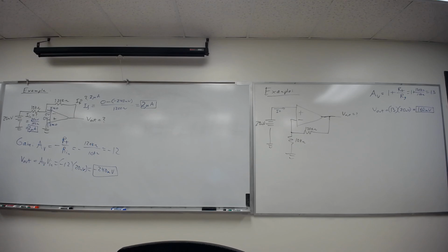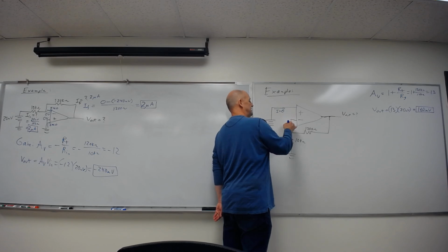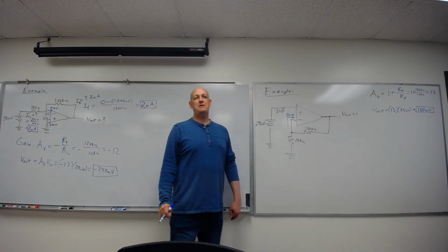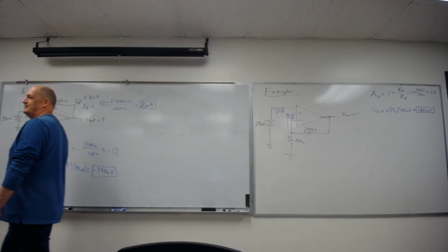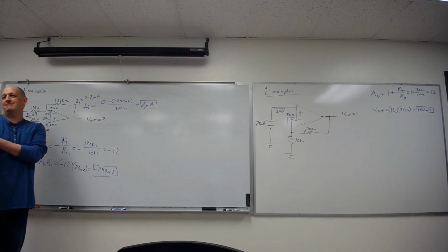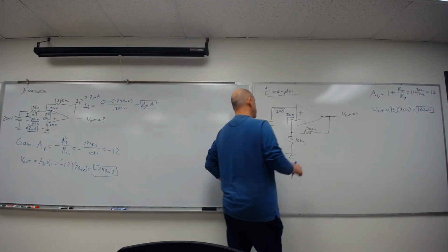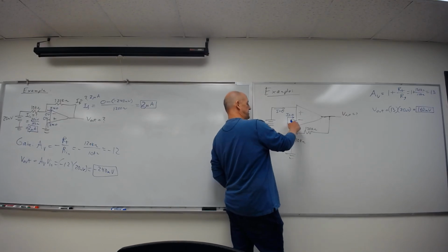Super high impedance, so it should go to 0. Yeah. My current's 0. Ideal op amps, the input current's always 0. Real op amps, the current's probably so low you can't even measure it in the lab easily unless you have very sensitive equipment. It'll be neat. Okay, my voltage up here is 20 millivolts. What's my voltage over here?